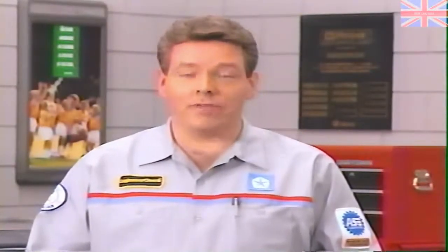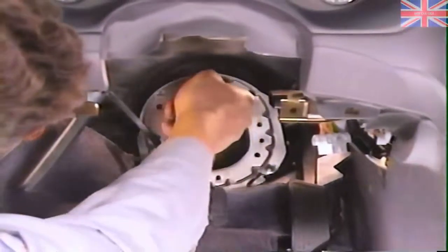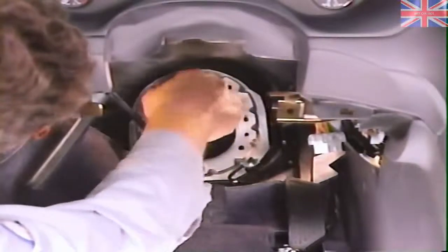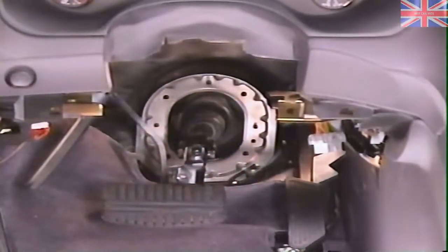Reverse the order of removal when installing the intermediate shaft and steering column. Slip the intermediate shaft into the steering gear by lining up the splines. Be sure the inner cover and retainer is installed with the larger circumference of the retainer facing down.